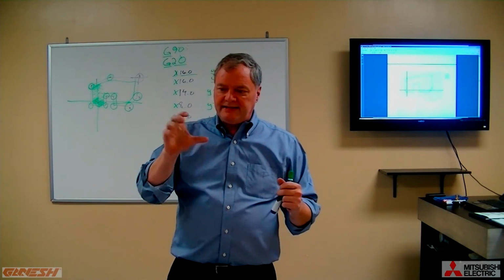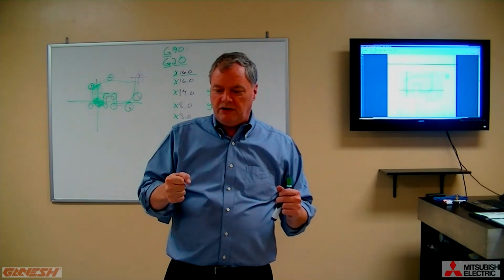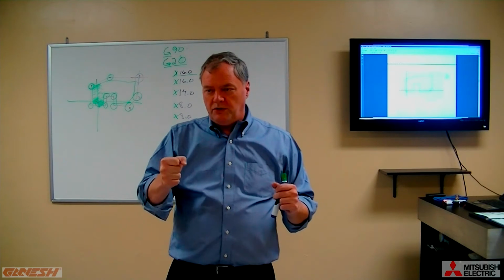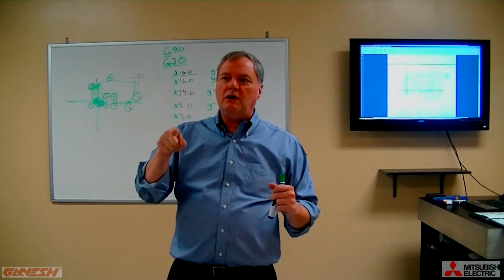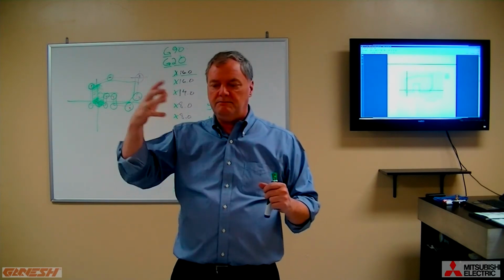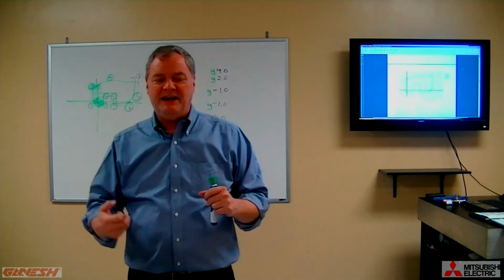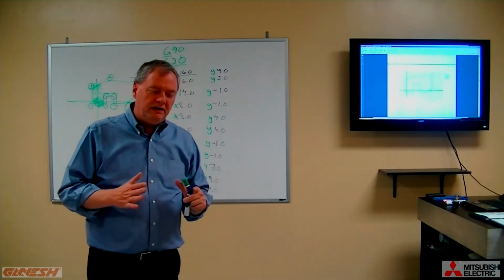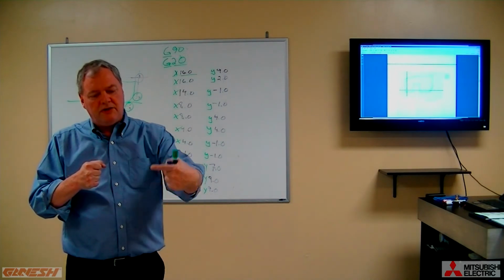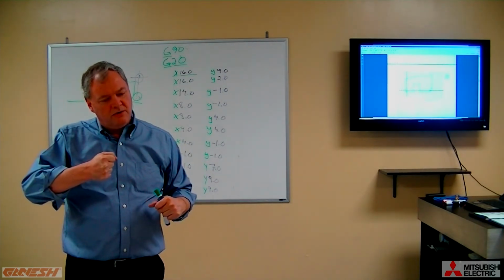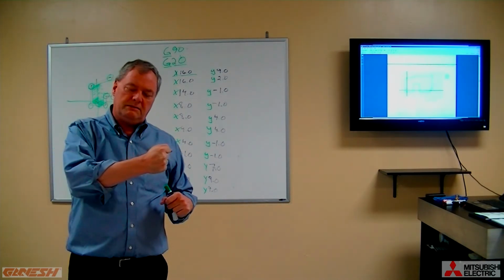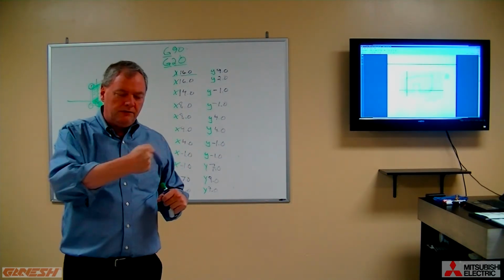And then if you took that same large drill and tried to drill a piece of wood, the drill would start working, but you'd actually have to slow it down, because if you were going too fast for that drill, it would not be able to effectively engage the material. So that's what we consider a cutting feed rate. You not only slow down the RPM, but you slow down how fast you're advancing the tool into the material. That's what we call the feed rate, right?